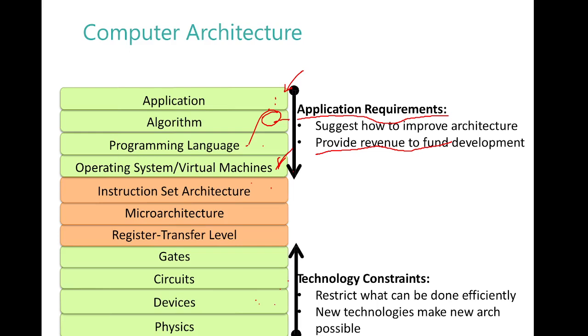If you have, let us say, billions of transistors in a chip and all of them are having some leakage, because even if they are not switching they leak current, then the power dissipation arising out of those transistors will be huge. So how do you tackle that? What is the effect of having such high leakage current? If your application is battery operated, your battery will drain quickly and so on.